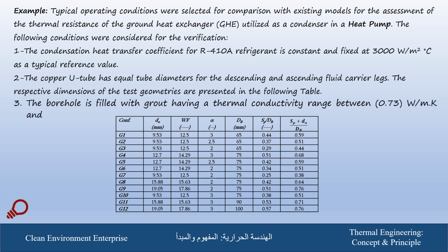And a range of thermal conductivity between 0.73 and 1.9 watt per meter Kelvin will be used to show the effect of thermal conductivity of the grout on the performance of the geothermal heat exchanger.